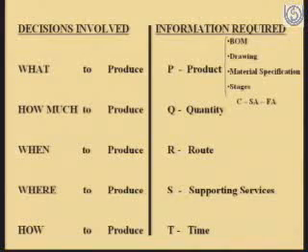P is the product to be manufactured, but not only the product, we are not happy with that. We want to break it down into slightly more detailed activities, what we call the BOM, Bill of Materials. For the Bill of Materials, we require the drawing so that it can be manufactured. Then material specification and the stages.